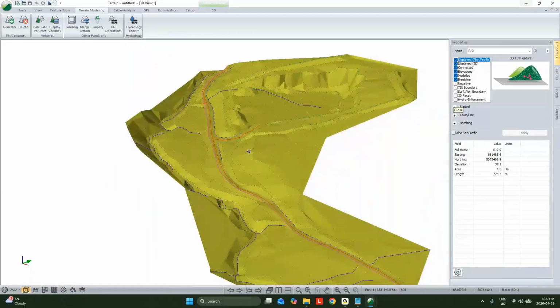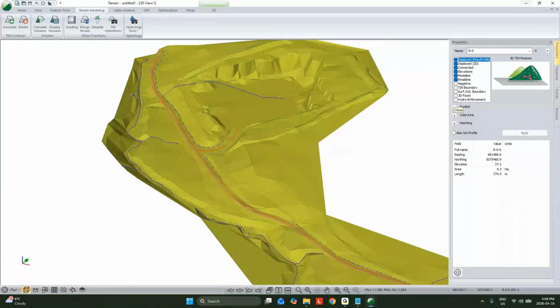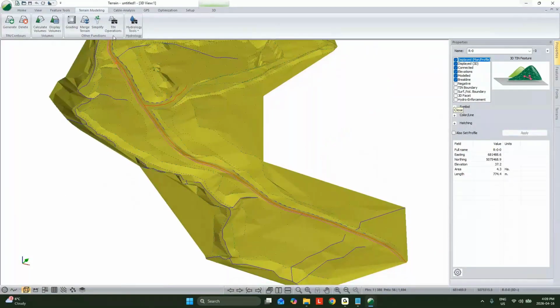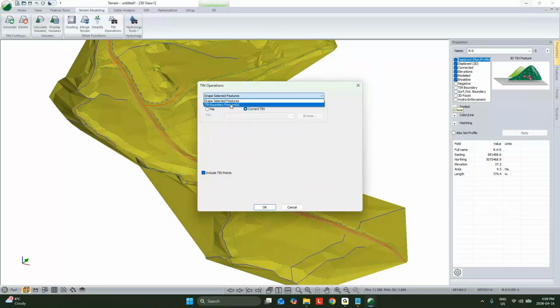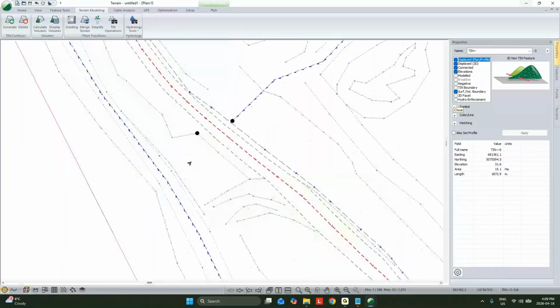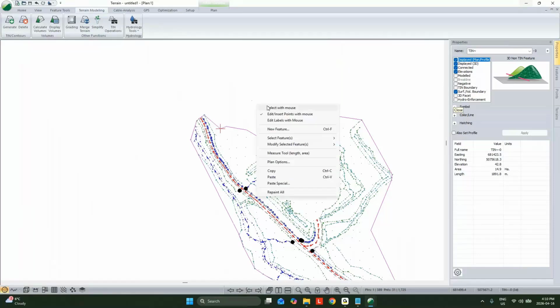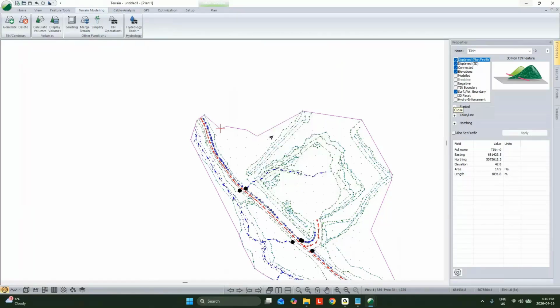to use that with our conventional LiDAR surface, we'd take this. We're going to be a little bit more pragmatic about trimming our edges out here. So we could say, well, there's our tin boundary as is. So this blue line going around here, and I'm not going to do as good of a job as I probably should for the sake of time. But we keep that as tight as we are comfortable with the surface data. Then we'd say, well, that's a tin boundary feature. So rather than having big interpolations across there, we could hem this in.